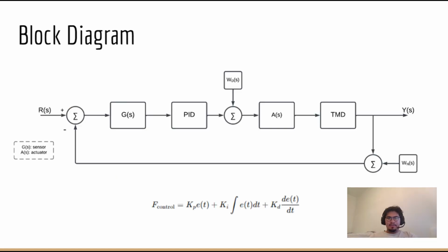Here we have a block diagram incorporating our PID controller. The input to the system is a force related to sensors to the PID controller. The controller, using the control equation shown, optimizes the TMD mass movement to counteract the force. Any disturbances are summed to produce a new signal. The actuator, in conjunction with the TMD, generates an output force to counteract the disturbances.